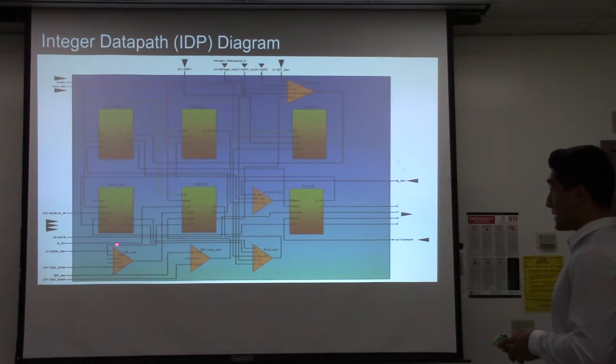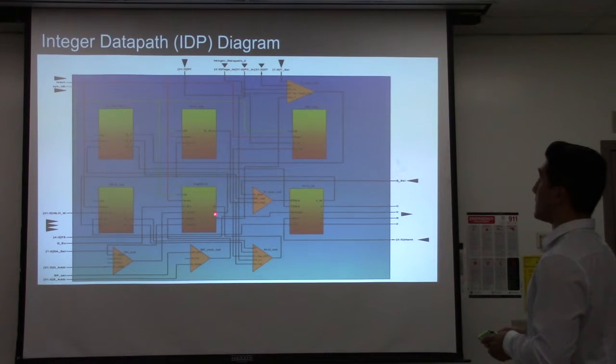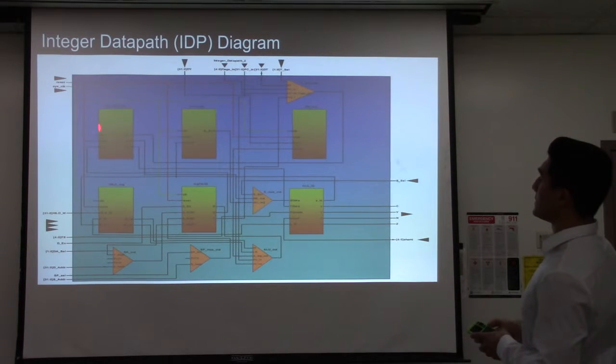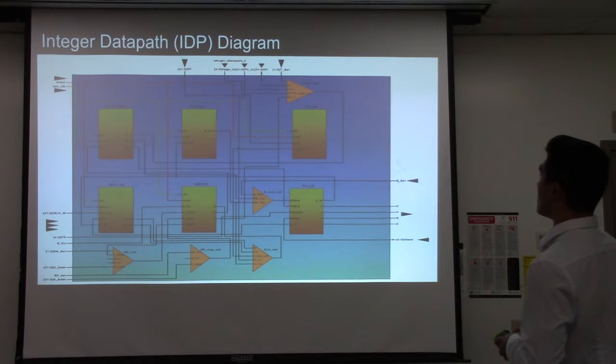The DA out is going to select whether we use D address or T address based on the opcode, and send that in as the D address. The S address is selected with our SP mux out, and the data from the S and T gets sent into our RSRT. It's kind of hard to see here. It's sent into this register, and from here they get sent into our ALU.